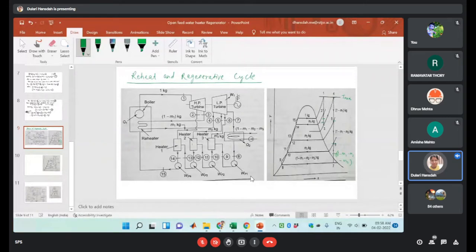So it is the point of condenser entry. So it is the condenser where your steam will lose the heat. So heat rejection will be there, and that will be formed to the condensate. So that condensate will become the saturated liquid at the point 8. So it is the point 8. Then we have used the pump, that is the 8 to 9. So it is the pump to increase the pressure of the feed water